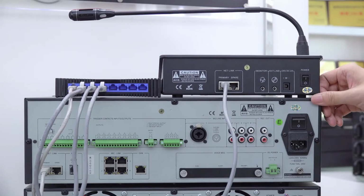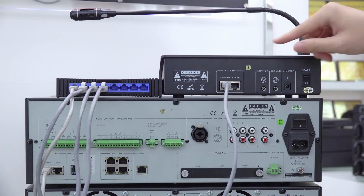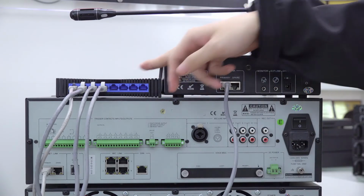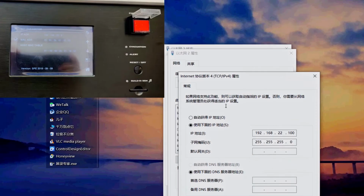As we discussed before, this controller supports the 4 desktop microphones, and also it supports the remote paging microphone. It's connected with the switcher directly. Firstly, we need to equip the network address. It needs to be in the same gateway as the system controller.